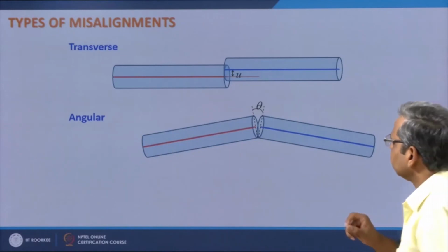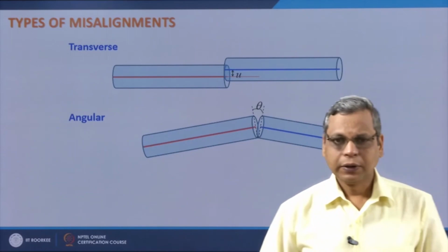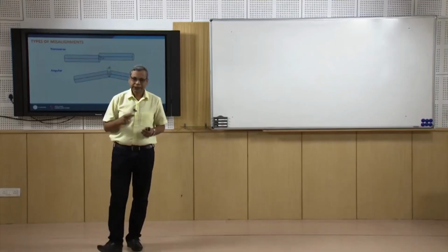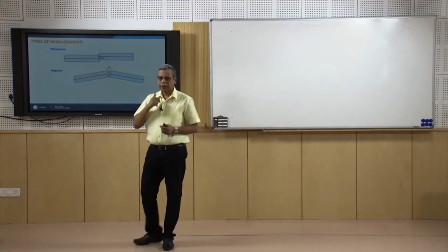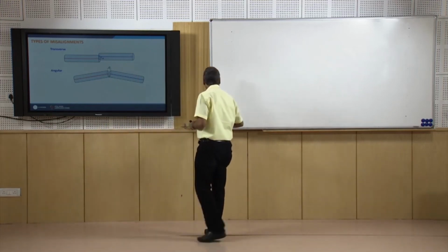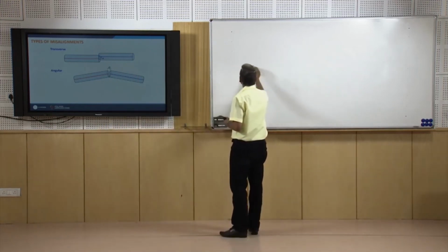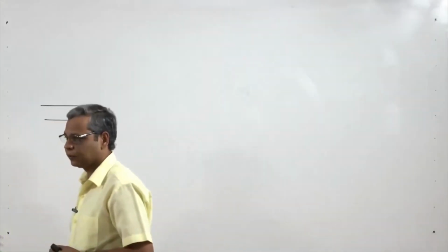This can be caused due to the finite precision of the stages at which you are putting the fiber, or due to cleaving of the fiber not being very sharp and perpendicular to the axis of the fiber.